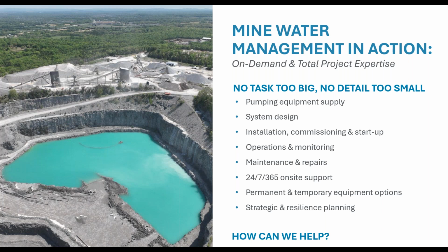I would say we should evaluate what your existing seal configuration is. In some cases, it could be, as you mentioned, different materials. For instance, a tungsten carbide has a little bit more hardness than maybe a silicon carbide, so that has better abrasive resistance. It's hard to implement flushes that you might see on surface mounted pumping systems into a submersible seal, just because it is such an integrated system with pump, motor, bearings, and seals.